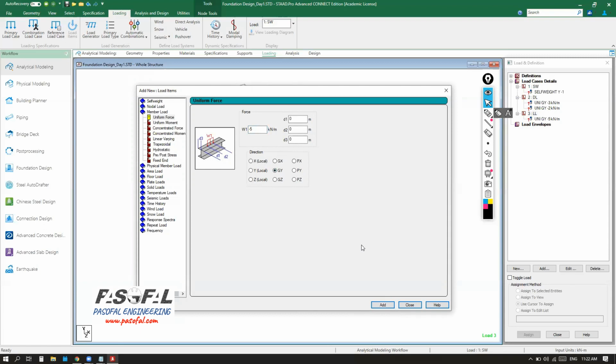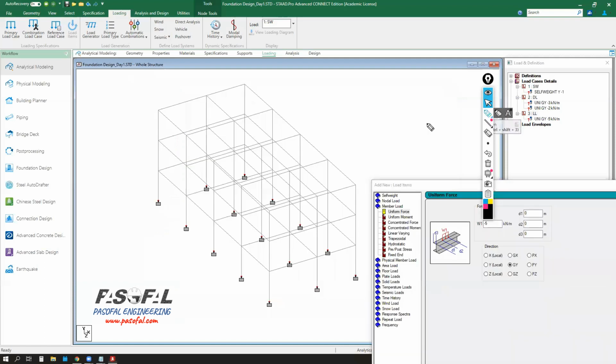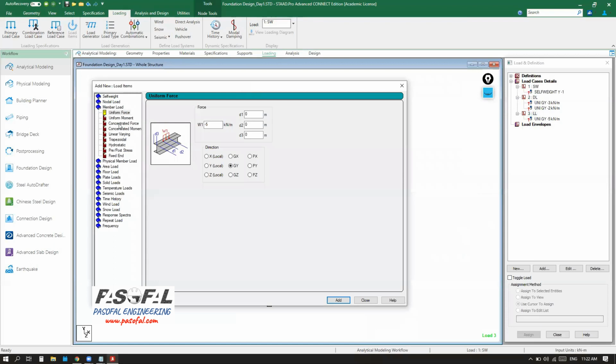And let's assume that we calculated our wind load, and then I want to assign this wind load to the structure. Which means I want to assign, for example, in the X direction to all these nodes. So that's why I'm going to define one nodal load.